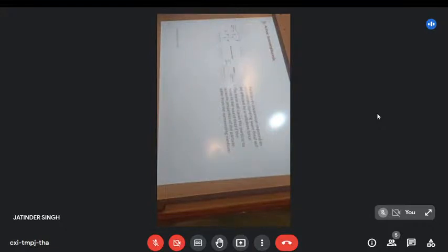Sound does the same thing in microchannels. So sound moves particles in microchannels as well. And that's why we can use acoustic fields. We can put little surface acoustic waves over the surfaces to play around with these forces and use them for particle manipulation. So if we've got a standing acoustic wave, our particles, depending on their properties, may move to the node that sits here, and they'll line up in the middle.